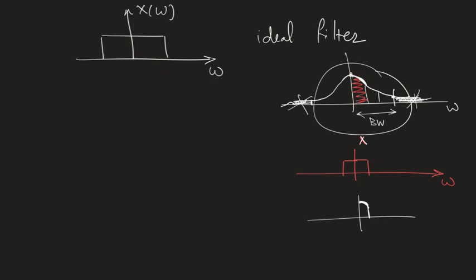Okay? So this way, you have picked a certain part of your signal around a certain frequency range. You can also pick the second one by multiplying by a square that appears here, and it will have a counterpart in the negative side. Or a square that appears at the higher part and a counterpart. So you pick the third part of the signal and so on, right? This operation of picking a particular frequency range is called filtering.